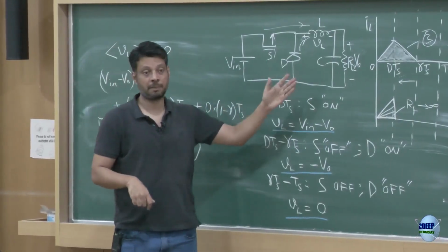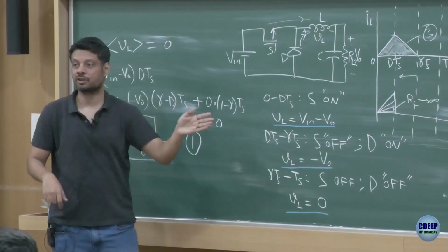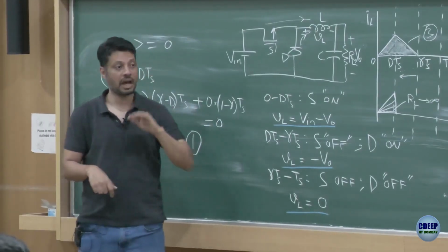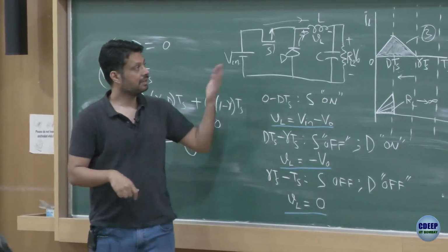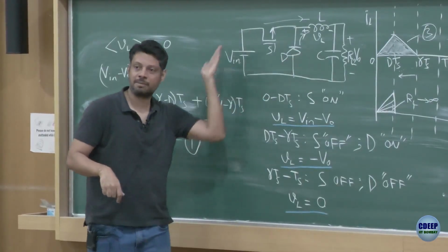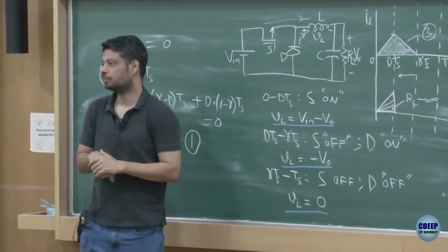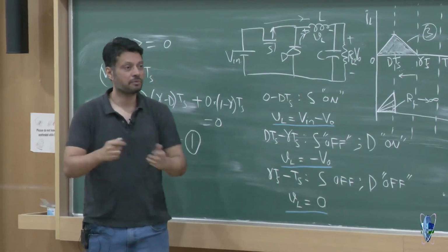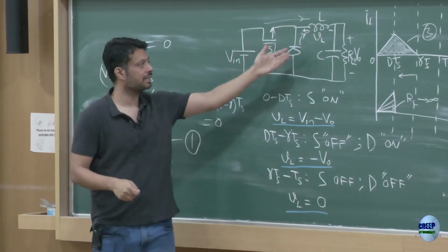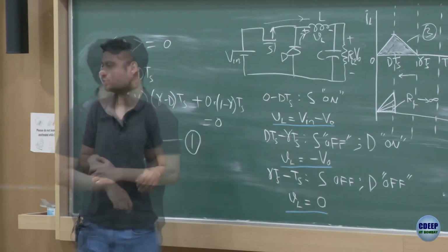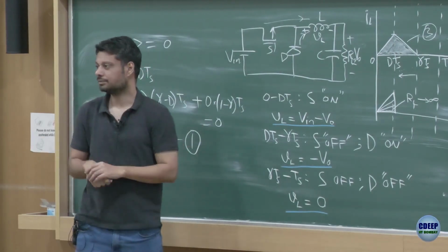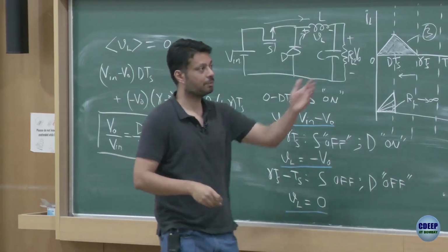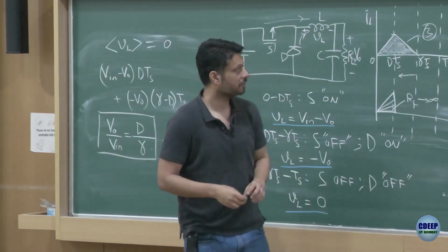So, that's happening because your output voltage is now dependent on gamma or dependent on RL, right. So if your RL tends towards infinity, this would give you almost the same voltage as that of the input supply, irrespective of the duty cycle, right. I mean, it will of course change a little bit with duty cycle, but more or less it will give you the same output voltage as input voltage. It's an out of syllabus question, but I can still explain, because I didn't want it to go that way, somebody asked me, therefore we went that way.